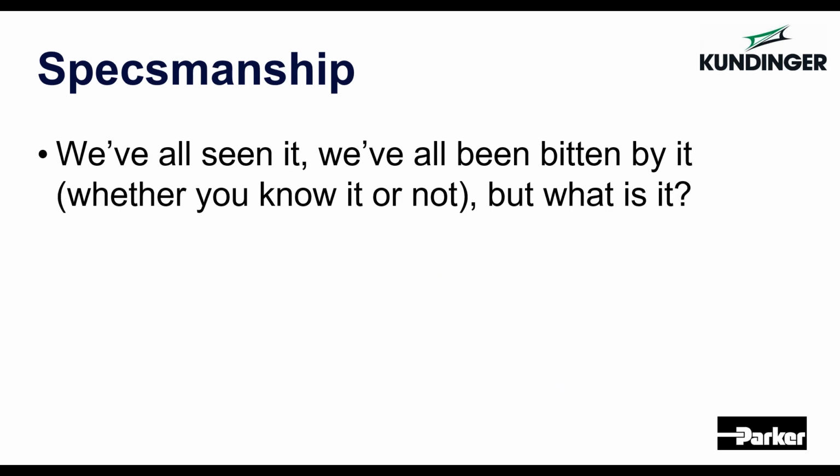So let's talk for a second about specsmanship. It's very difficult to just size something out of someone's catalog because you don't really know what kind of marketing fluff has gone into their specification numbers. So I'll give an example. We'll talk about a product later in the presentation called the HMR24. That unit is capable of holding about 3 tons of mass, and it's also capable of 5 Gs of acceleration.